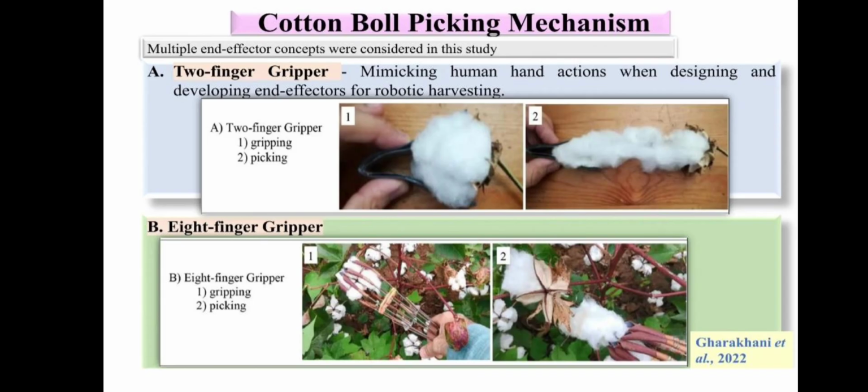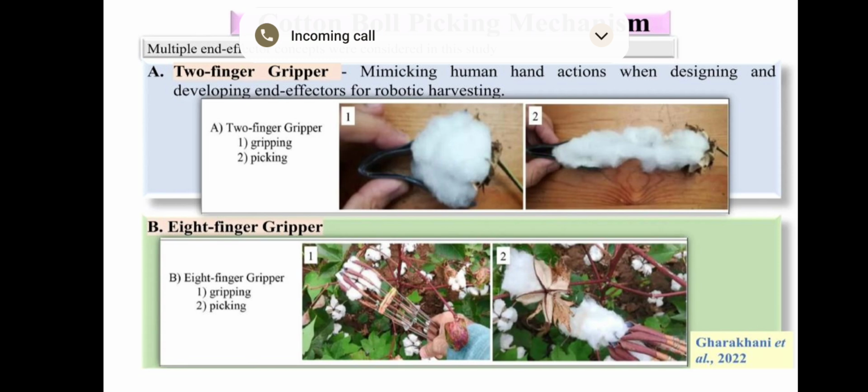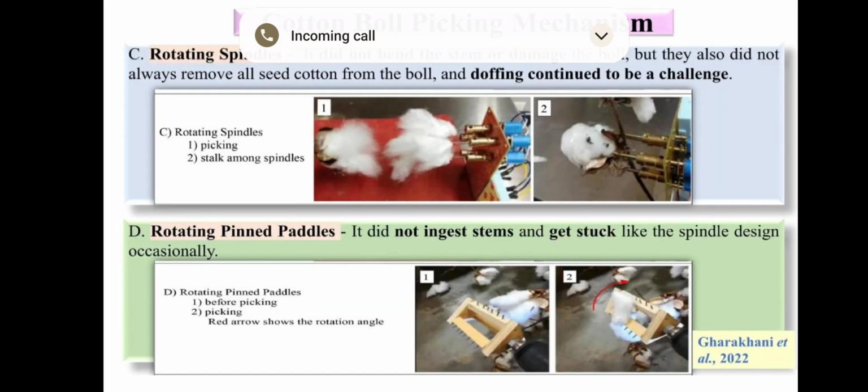So the robotic cotton ball picking mechanism primarily uses a combination of machine vision, AI powered algorithms and robotic arms with specialized end effectors to identify and physically extract mature cotton balls. The camera captures images of the field to locate open balls, which are analyzed by algorithms. Robotic arms then move to this precise location to pick the cotton, often using a suction or plucking motion to detach it from the plant and deposit it into the collection system.